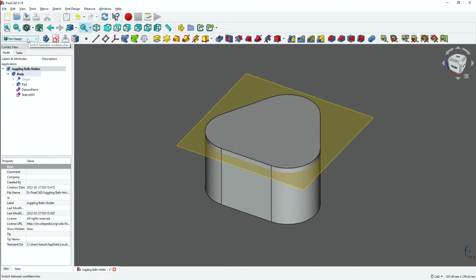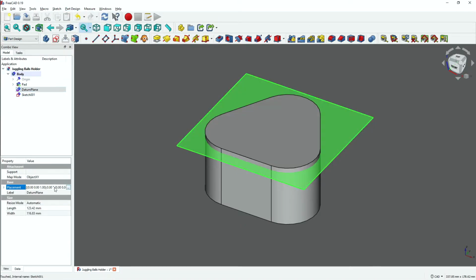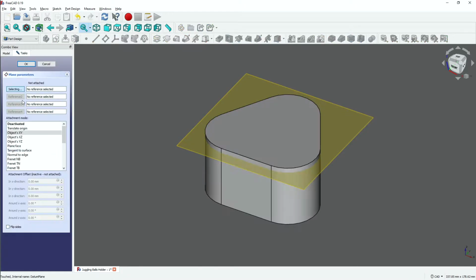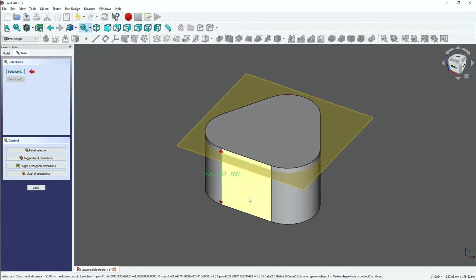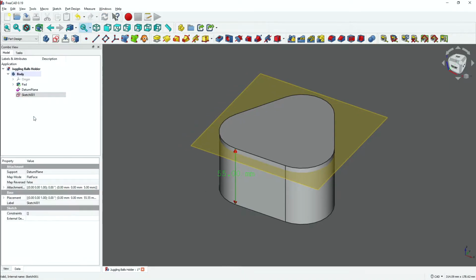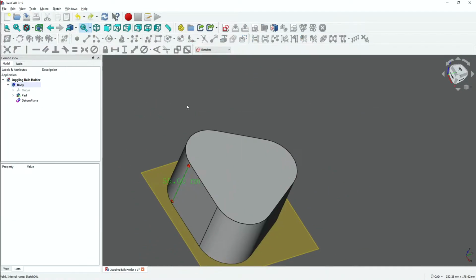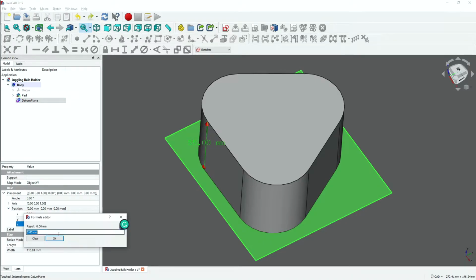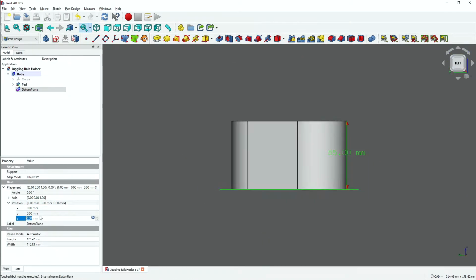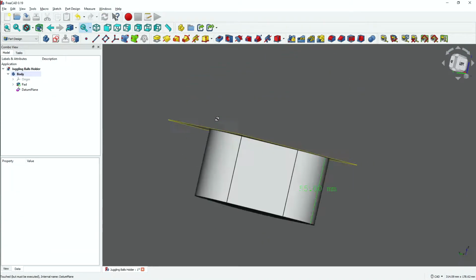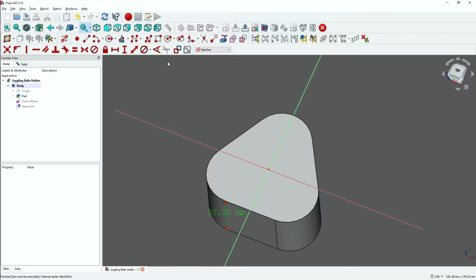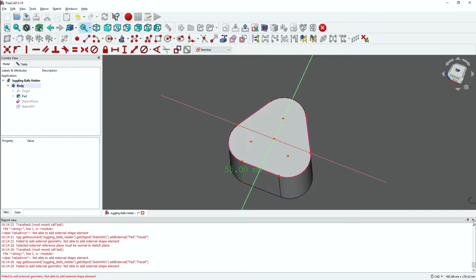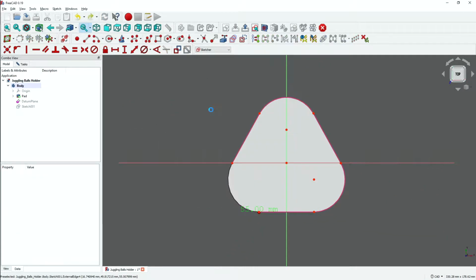In other software, it's not an issue, but in this one, what happens is, as far as I understand it, when you edit a part, if you have something tied to that face, once you edit it, the face gets a new name, and so things down the timeline will lose track of what it is or replace themselves, and it just can create a huge mess. And so it's best practice to create what's called a datum plane and just put it exactly where you want it, which means you got to kind of think about where everything is, which is fine.